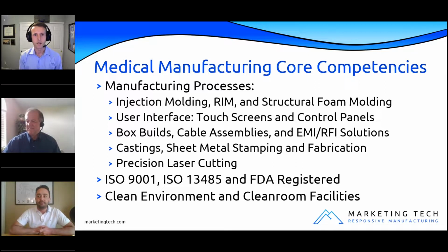Listed here on the screen are some core manufacturing processes that we specialize in. Some of these will be plenty familiar to you and your teams. Others you may not have worked with before. So we kind of bucket these into three categories: plastics, electronics, and metals. In the plastics world, we have traditional injection molding, which many of our customers are familiar with. Some more specialized processes like reaction injection molding, or RIM, and structural foam molding. Each of these plastic processes can play a role in medical equipment development. It just sort of depends on the size, appearance, and function of the part that you're designing.